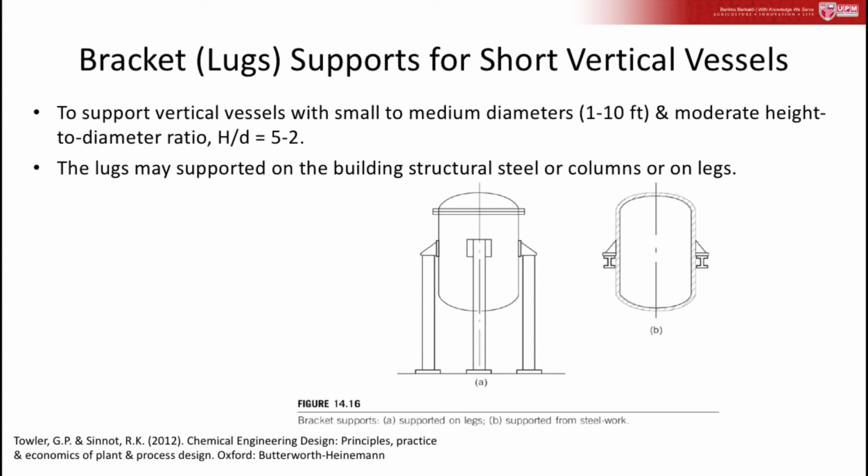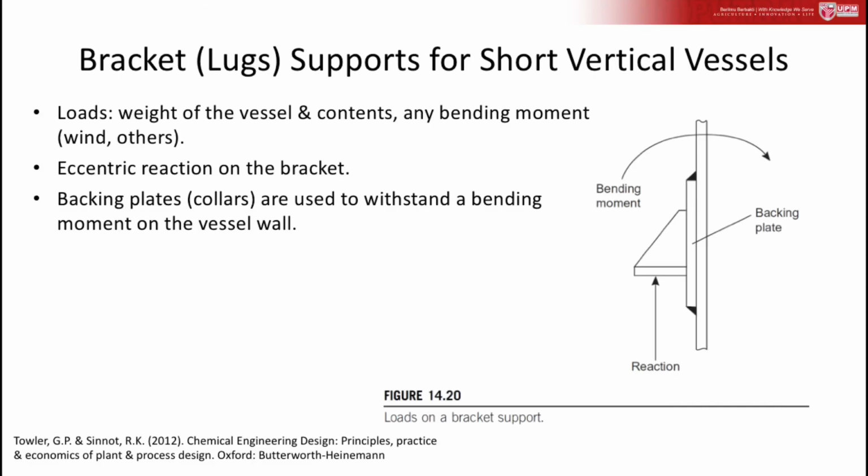The main load carried by the bracket will be the weight of the vessel contents, and in addition the bracket must also be designed to resist the load due to any bending moment from wind or other loads. If the bending moment is quite significant, you need to consider skirt supports, because skirt support is more stable compared to bracket supports or lugs.